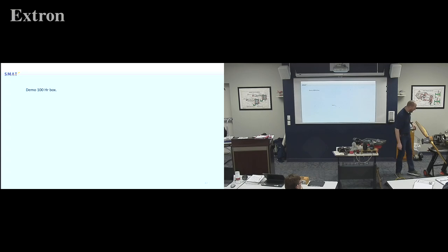So what this is for is, as I'm coming through, if I had my thumb on here, right now nothing would be happening because my exhaust valve is open. So I've got nothing, and I still have nothing, nothing's going on. I'm on the intake stroke. Ooh, now I'm on the compression stroke, and it's building pressure, and it's going to try to blow my thumb off the end of here. So I would use that to say, okay, compression stroke. So I found the compression stroke. So I know I'm on the compression stroke. So now what I'm going to do is take this out.